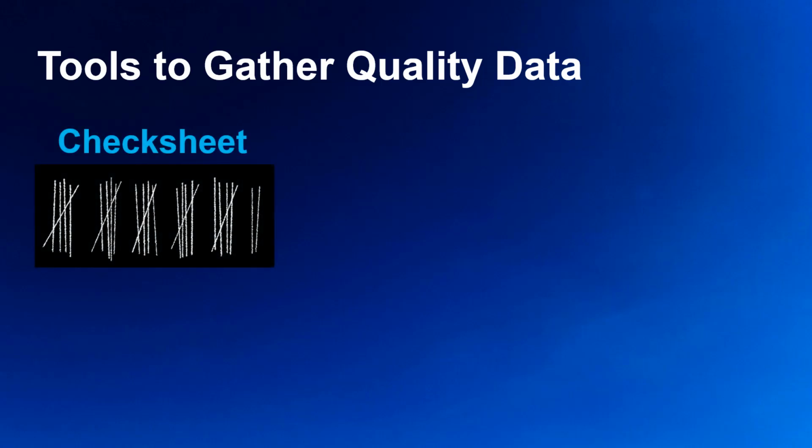We have many ways to gather quality data, ranging from very low-tech to very high-tech. For this lesson, we look at 6 tools briefly. One of the most low-tech tools is the check sheet, where we tally up each incident of a type of defect. For example, you could tally up the frequency of each failure mode, the physical location of each defect, the sample measurement variation in groups of 5 millimeters, or the step in a procedure at which failure occurred.